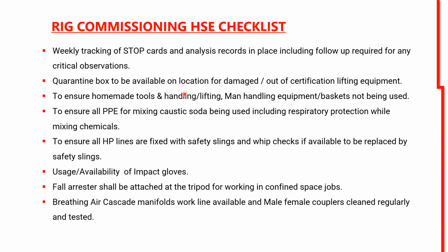Quarantine box to be available on location for damaged or out of certification lifting equipment. To ensure homemade tools and handling, lifting, handling equipment baskets are not being used. It should not be any homemade or repaired by the rig crew. Okay, if there is any problem, it should be repaired and tested and certified by the third party. Then only that can be used.